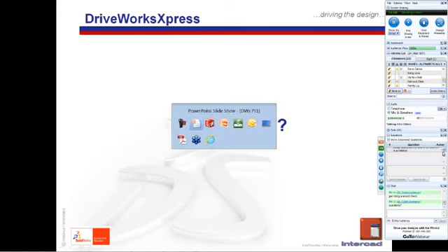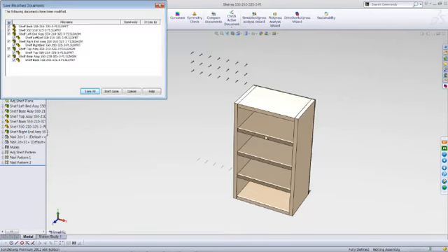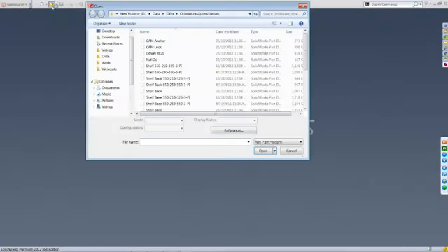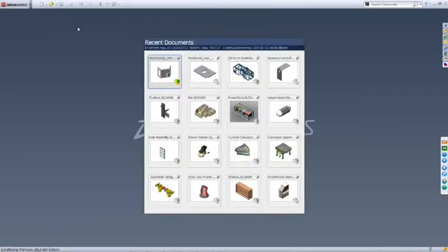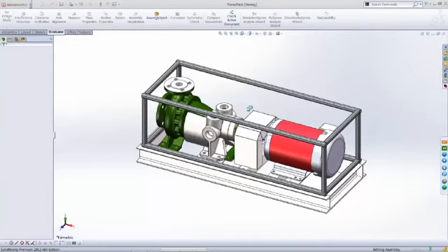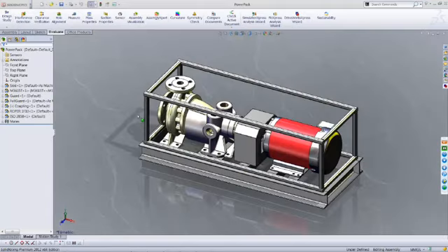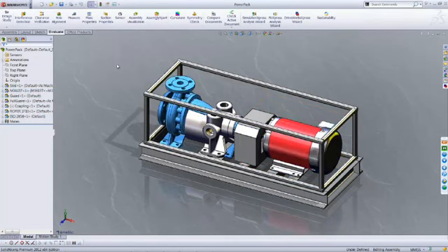Okay, just let me sidetrack back to SolidWorks again. Let me just close this for a while, and I'll just go back to this. This is another example that I really like because it makes use of configurations. The example I have, browse recent examples, is this one here. In this one, there's not a lot of changes in dimensions. What you have are changes in the parameters of configurations, because if you notice, each of these sub-assemblies, the motor sub-assemblies and all that, come with different configurations.